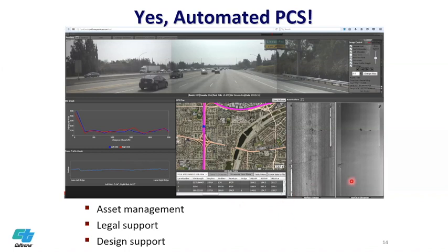Okay, so this is the automated pavement condition survey. We have the data in, and this can be done in about half a year. So it's really an improvement in data collection, especially for current surface pavement condition data. We also did a GPR, ground penetrating radar, investigation throughout our highway network.